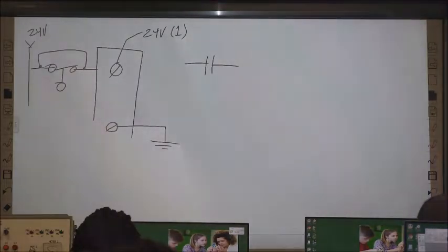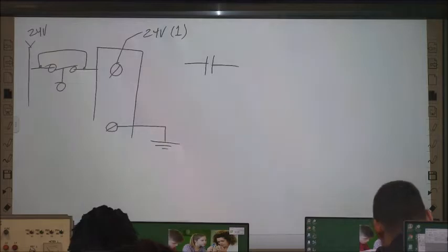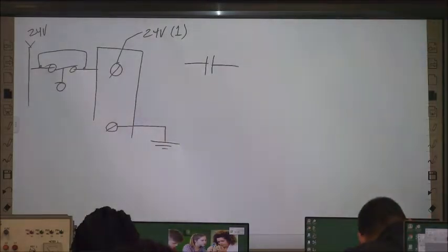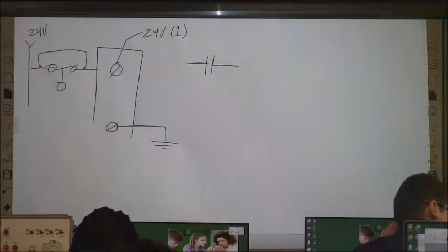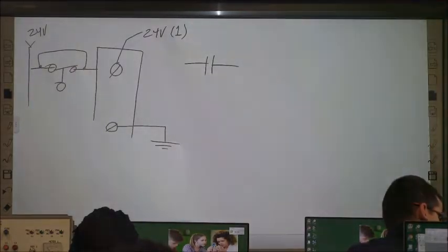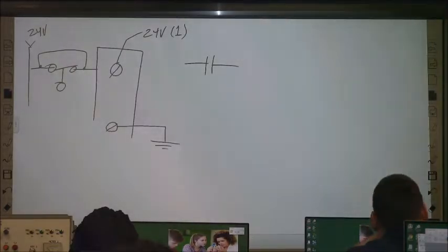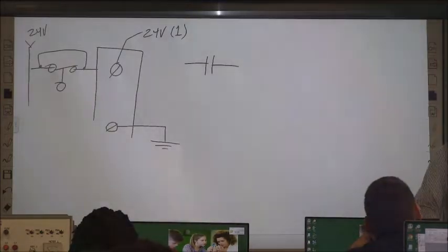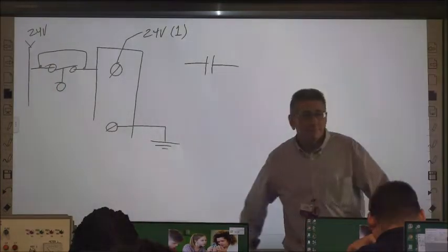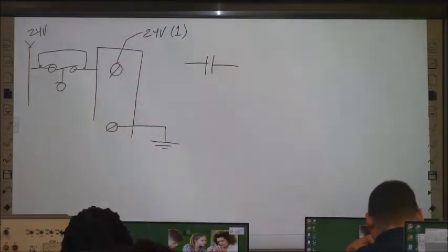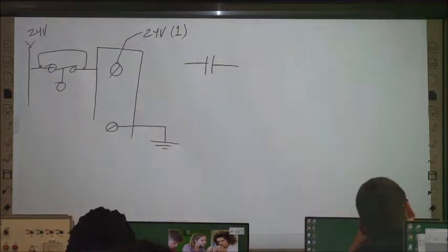Let's see, number 20. A normally open pressure switch is connected to a 24-volt DC sinking input module. The switch is in its normal state. The logic for the float switch uses an XIC instruction, but the instruction does not have logical continuity. That's how a normally open switch works that uses an XIC. Good thought process?